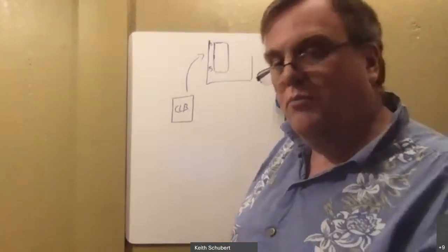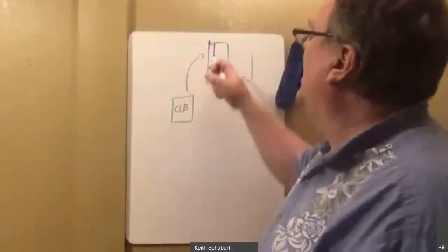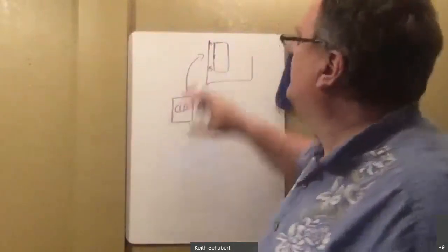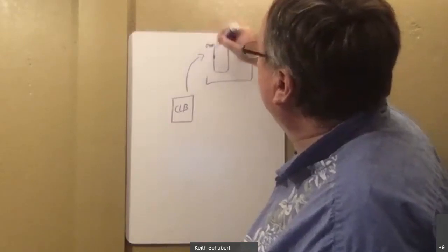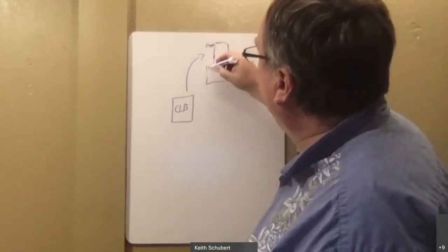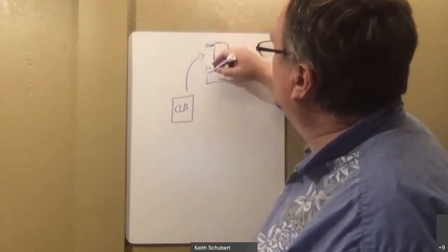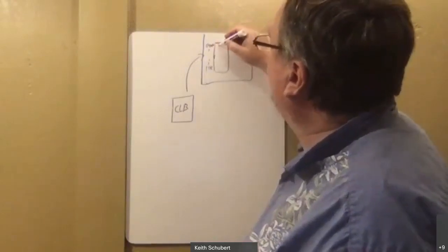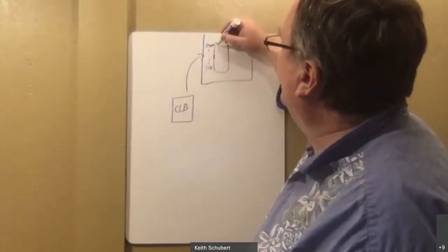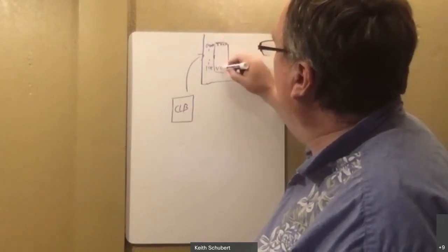This is kind of like when we literally make a logic table and write all the binary combinations. I'm just writing them in decimal to save myself time. But if you want to, just think of them in binary, you've got 4 zeros through 4 ones. That's the basic of their lookup table. And then for each one of these, they've got what the outputs are, and you can program what these outputs are.